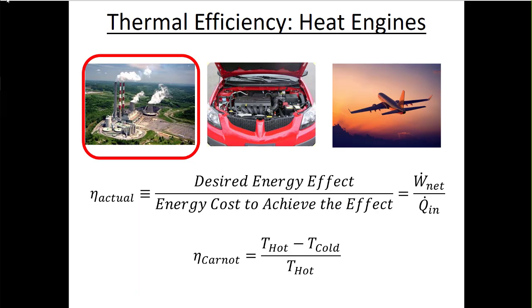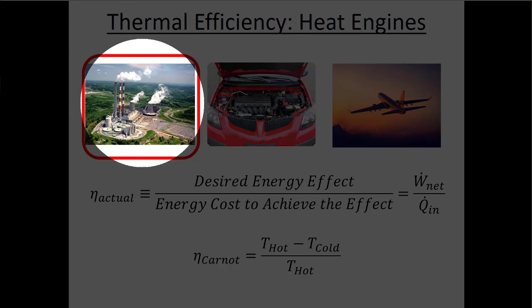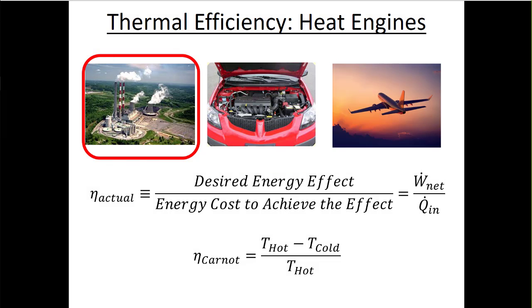In particular, we're using what we know about thermodynamics to learn how we keep the lights on, how we power these computers that we're using to give or receive the lecture today. And we do that by using heat engines. Like I said before, for the Rankine cycles we're talking about, a little bit less than half of the power generated in the US, at least in 2019, was generated using Rankine cycles, typically coal-fired and nuclear-fired power plants.